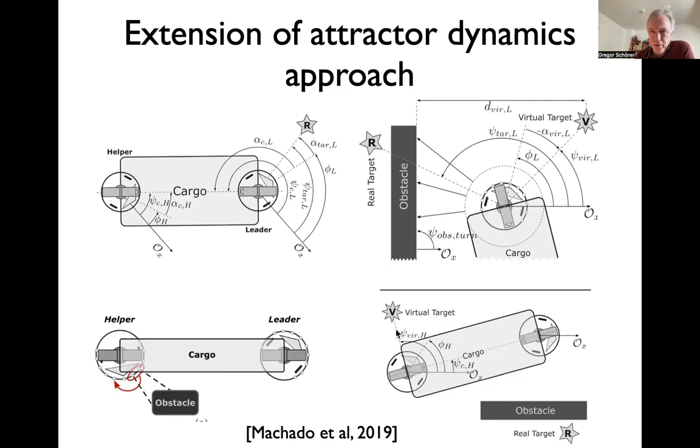And all of this is based on geometrical analysis of hypothetical obstacles and targets. For the obstacle, it's really just based on the sensory measures, on the distances, so that it's an obstacle, a wall-like obstacle. It's just computed from two neighboring values of these distance sensors. Any pair is analyzed that way. And if they have somewhat similar distance measures, that represents effectively something like a wall, and then you compute that virtual target. So it's a lot of formulas, but they're all just simple geometrical analysis.